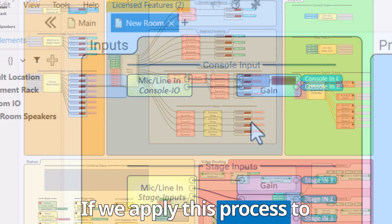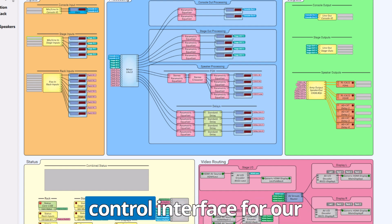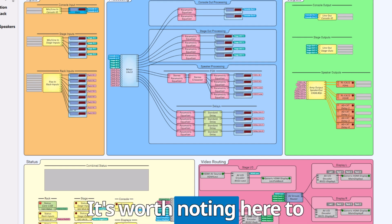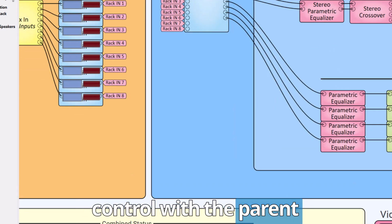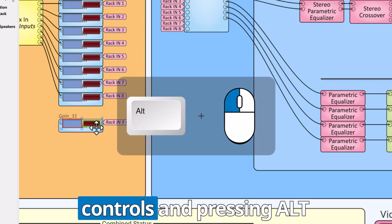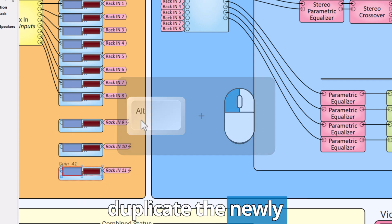If we apply this process to all the inputs and outputs of our design, we end up with a very clear user control interface for our technical teams, allowing anyone to look at this design file and understand the system. It's worth noting here, to make this build easier, if you make a duplicate of a control with the parent component it originally came from, then the new instances will continue that relationship. By selecting the group of controls and pressing Alt while clicking and dragging, you can quickly duplicate the newly created layout.